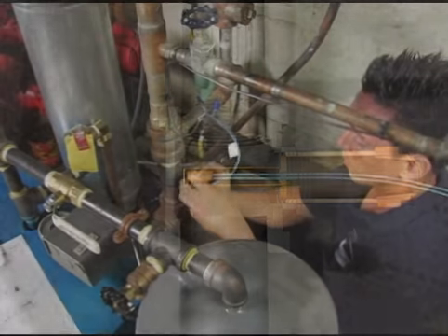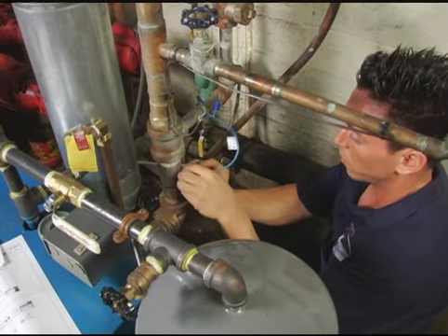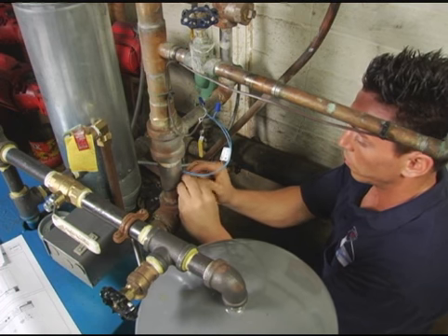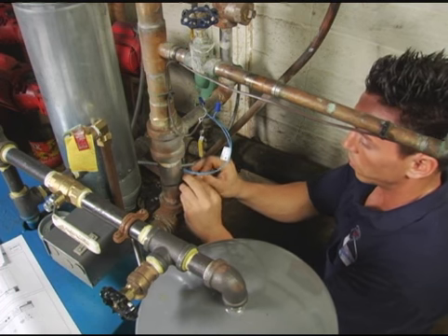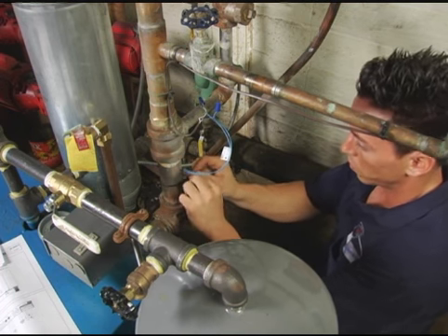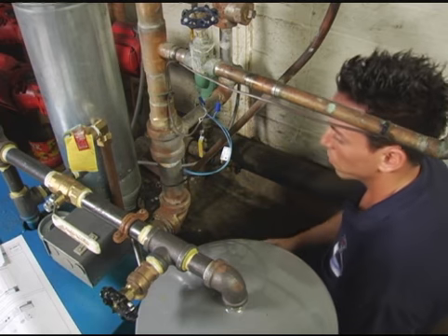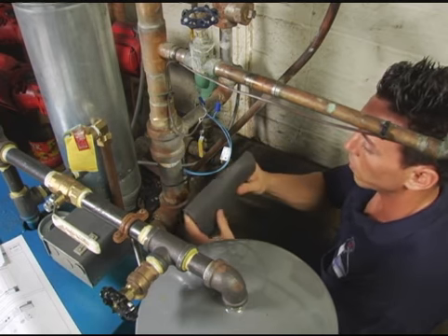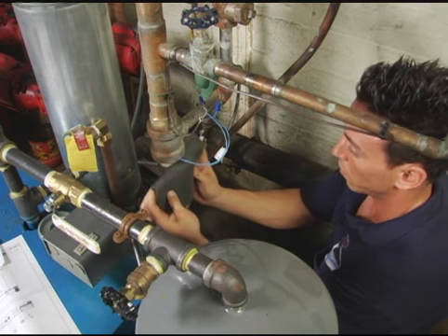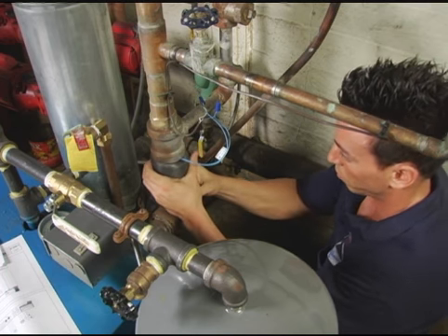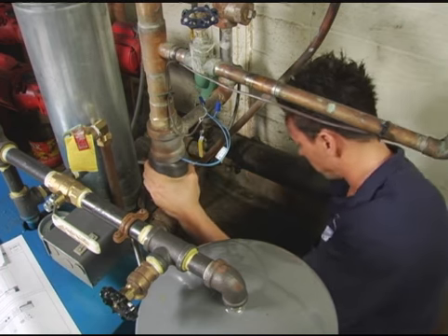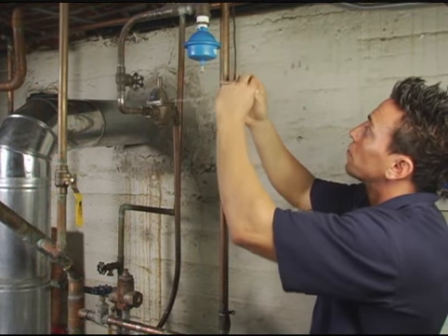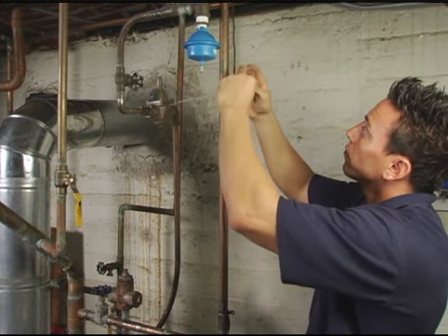As a general rule, the sensor should be installed on the boiler's riser before any takeoffs for zones or indirect water heaters. Make sure there is good contact between the sensor and the pipe and connect the required wiring to the sensor. If strapped to piping, it is good practice to insulate the sensor from cold drafts. Run the wiring to the control according to the manufacturer's instructions.